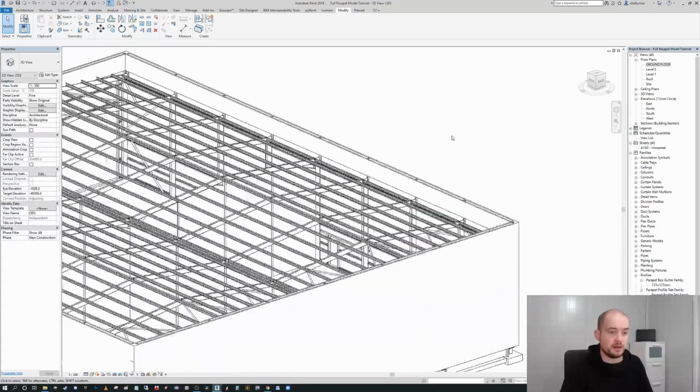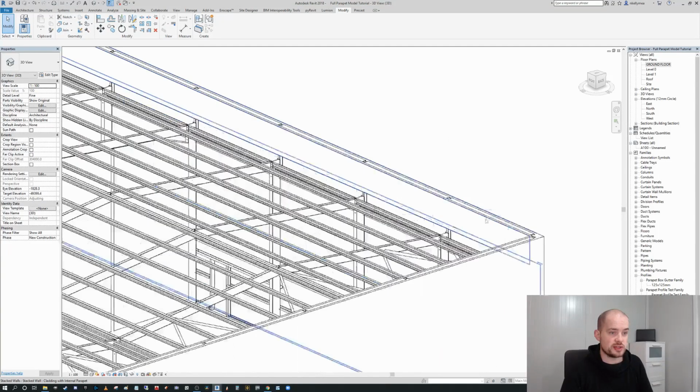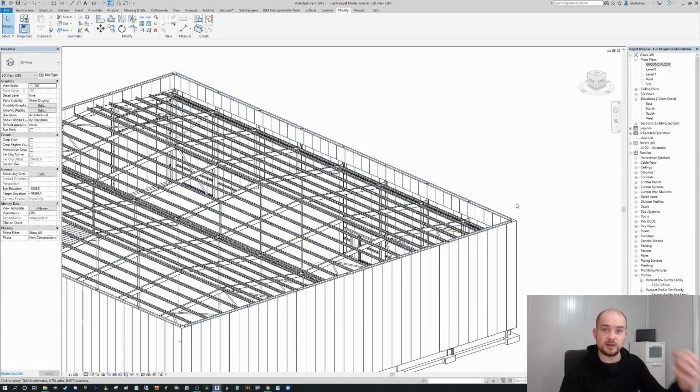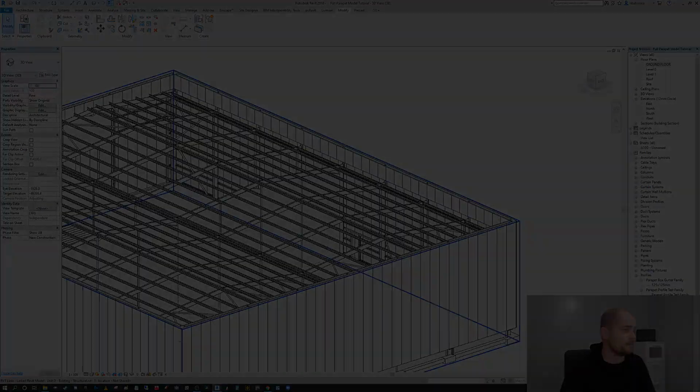And the next part we'll actually dress this up a bit, and we'll develop out the actual parapet capping on this, okay? So before we go ahead and populate the likes of the gutters and the parapet capping and the parapet insulation and that kind of thing, what we need to do is create our roof. And I want to make sure that we've locked the extents of the roof, the bounding extents of the roof, to the wall geometry adjacent. So when our grids change, our walls change, and our roof stretches accordingly, okay?